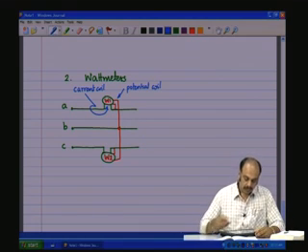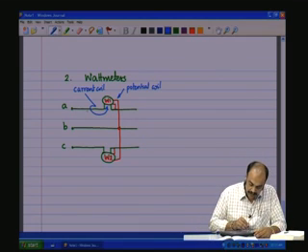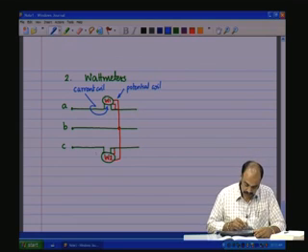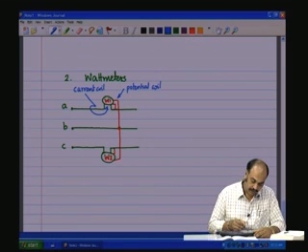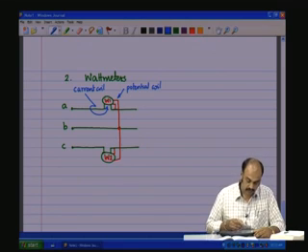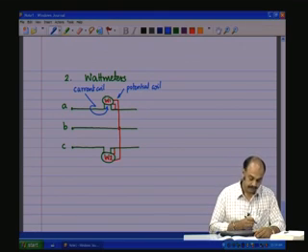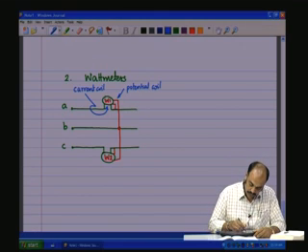Okay. So, the current of the A phase and the current of the C phase are taken, the B phase is taken as the reference point, and the potential of the A phase with respect to B, and the C phase with respect to B, is measured like that, and this of course goes to the 3-phase load.